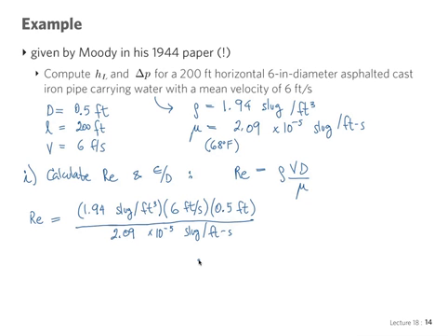And indeed all units cancel out because this is Reynolds number and non-dimensional. So they should all cancel out. We have feet cubed, and then we have 1, 2, and this one at the bottom, because at the top it also cancels out, seconds cancel out, and so on. Right? So the numbers, we put them in the calculator and we get 279,000. Definitely turbulent, right? Without a doubt, this is going to be turbulent.